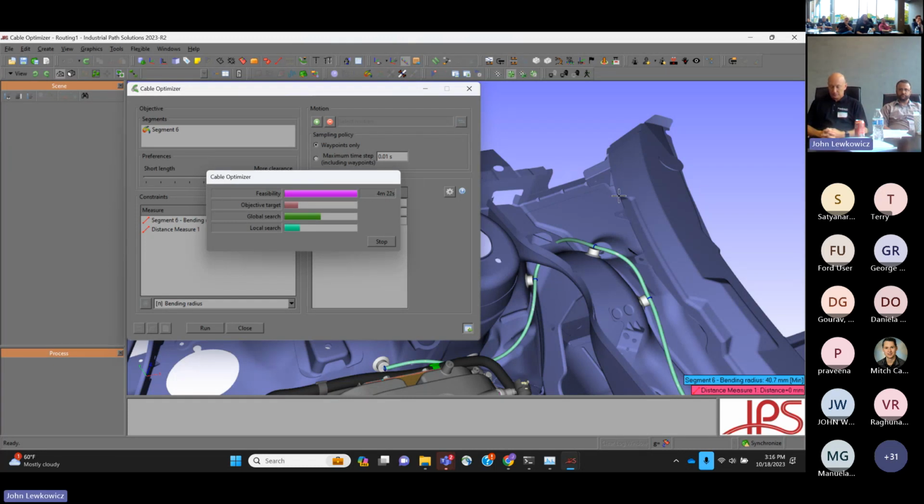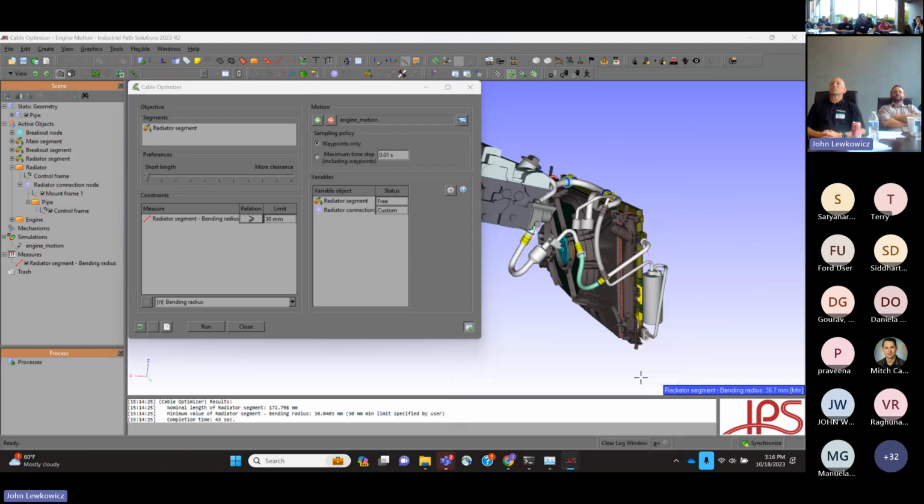Or translation within some constraint value, right? So I could create, and we'll see when we talk about clips and connectors, a clip that will rotate, and I could give it some range of motion in that rotation. For this particular optimization problem, I'm saying take the entire clip and you can rotate it freely. So yeah, if we set it up in the database with that kinematic built in, it would account for that. But in this case, it's just a static clip, and I'm saying, see if you can change its orientation or translate it in X, Y, and find something that's a better solution.